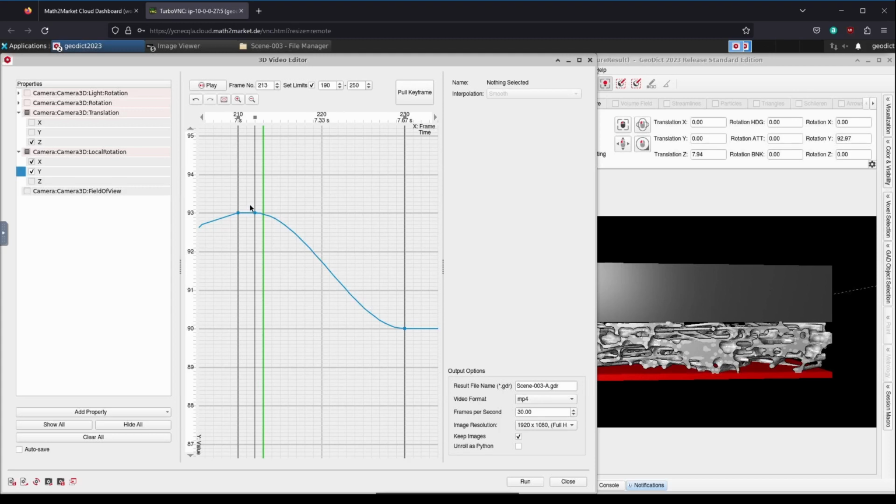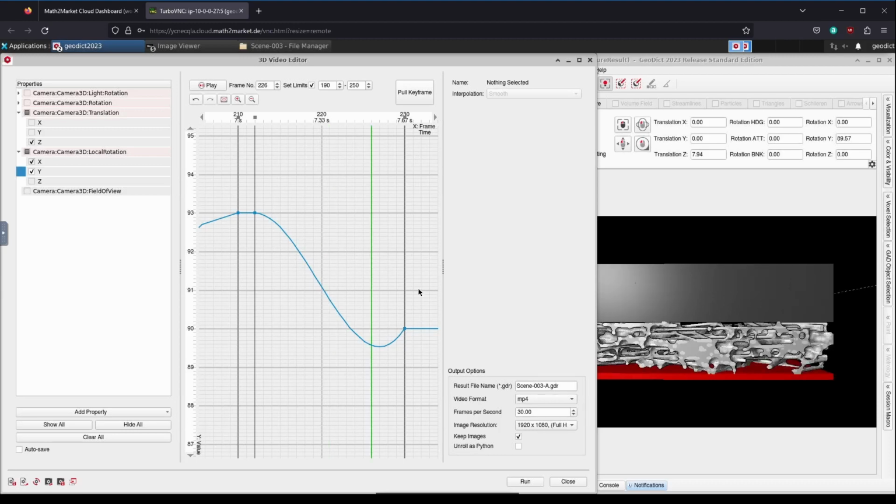As a final icing on the cake, we adjust the second slope of control point 212, the one that affects the curve towards the next control point. We change the value to -2. This pushes the curve past the end of the value before it ends at the control point. This gives another little bounce at the end and makes our animation look more dynamic.